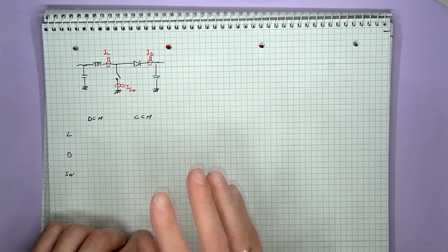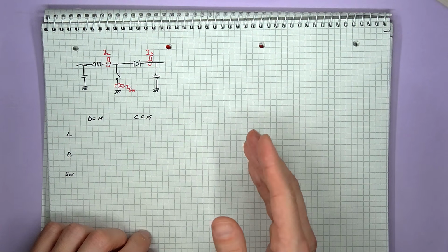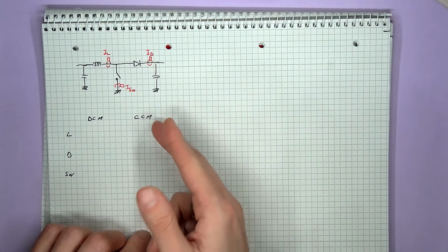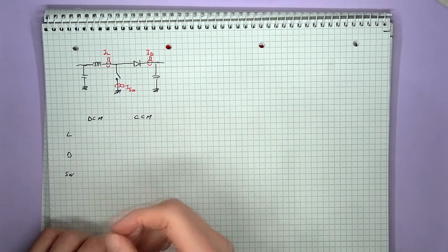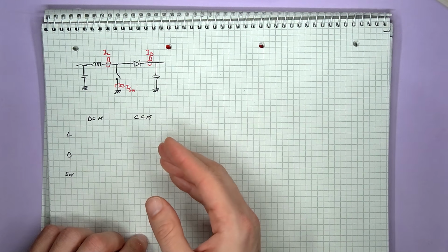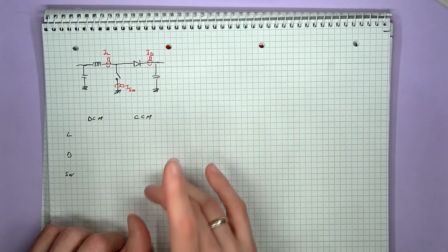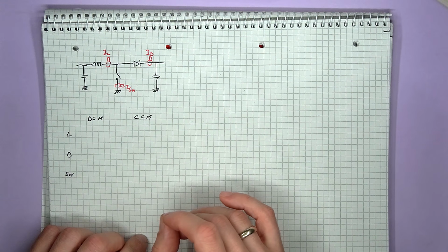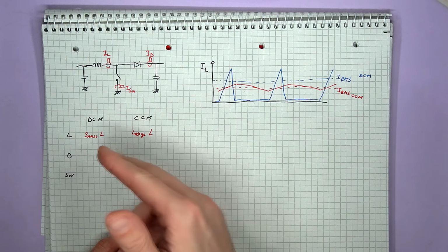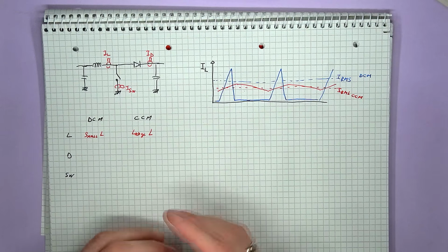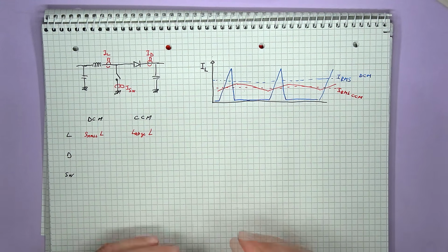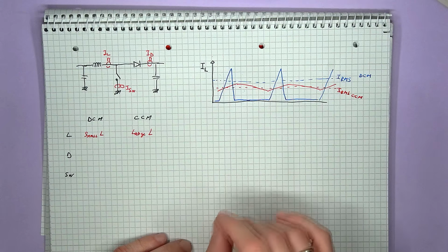Speaking of efficiency, one of the things to observe, if we compare a converter built for a fixed load, that is once designed to work in continuous conduction mode and once in discontinuous conduction mode, the exact current values that pass through the converter will be different, and so will some of the components. First off, the way in which you force discontinuous conduction mode is to use small inductor values. The smaller the inductor is, the faster the current will change through it. In other words, the current will vary quicker.